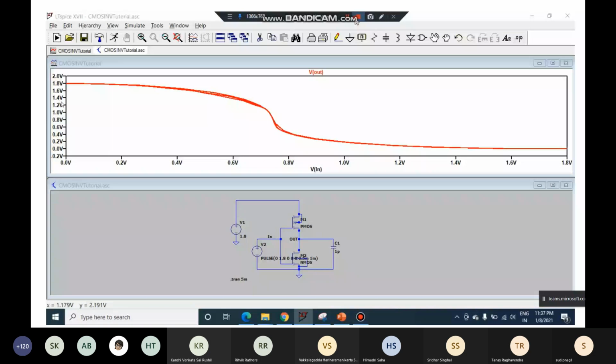So transfer characteristics essentially shows how good your inverter is for different sizes of the transistor. So this is how we do sizing in integrated circuits. We design some circuit by using some schematic topologies, or basically some connection diagrams. But after doing that, you can always play around with the width of the transistors, whereas the length of the transistor should be constant over the entire chip.